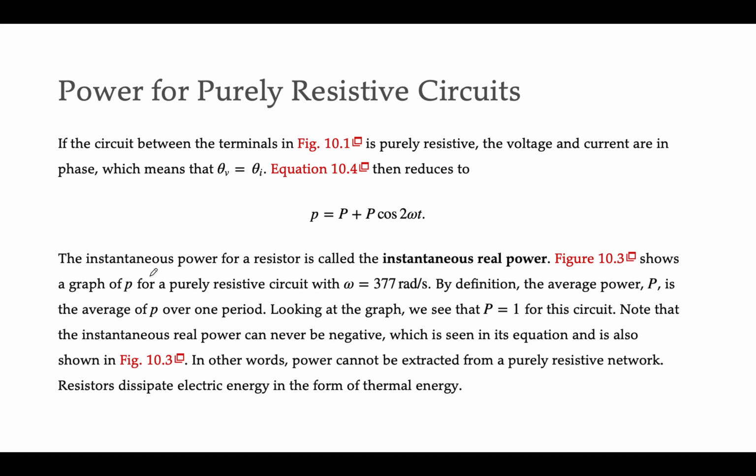In fact, it is one of the key issues with power distribution, particularly when you're trying to take things like wind farms, put them on the grid, and deliver the power over a large geographical area, because you tend to get big phase shifts. Big phase shifts between current and voltage mean there's a certain amount of power that you can't extract from the system because it's reactive.